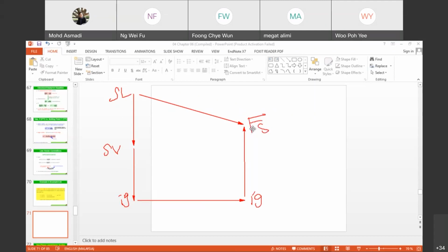Final state. So this one is 273.15 Kelvin, 1.2771 bar. This one delta H, delta S. And then saturated vapor with the same temperature and pressure. This one is also the same here, because you just change the phase, right?